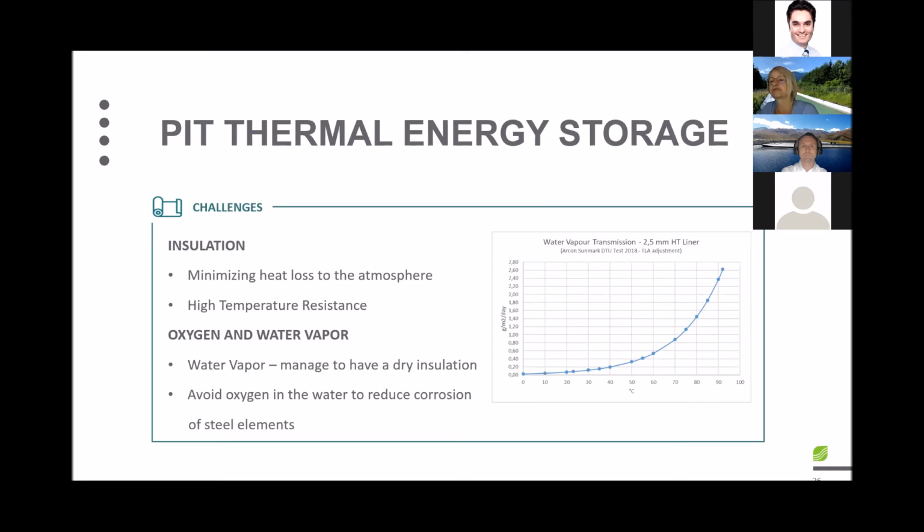On the other hand, we have to consider the oxygen which is created. As I said, the oxygen which is filled with the water into the pond, while introducing the chemical and while heating up the water, goes to the surface of the water, so it accumulates below the floating cover. The oxygen has to be driven out of the application. We do not want that oxygen in the water, because it will cause corrosion of the steel elements like the diffuser towers or the pipes in this application. The good thing is that if the oxygen is released from the application, it also helps to enhance the service life of the geomembrane.